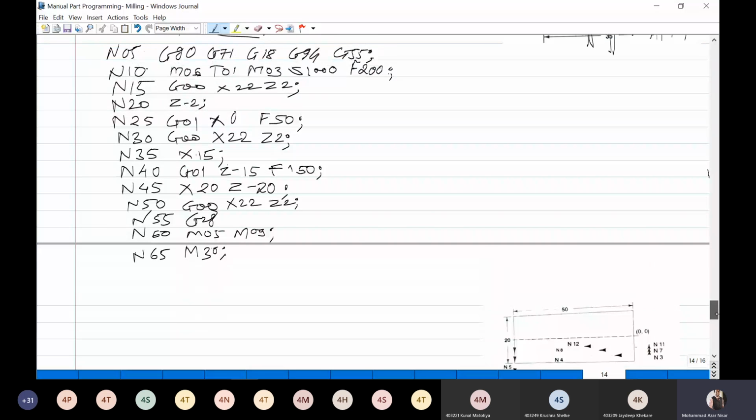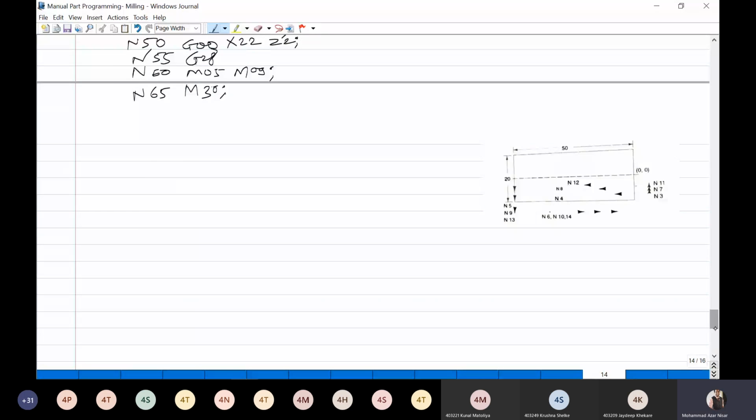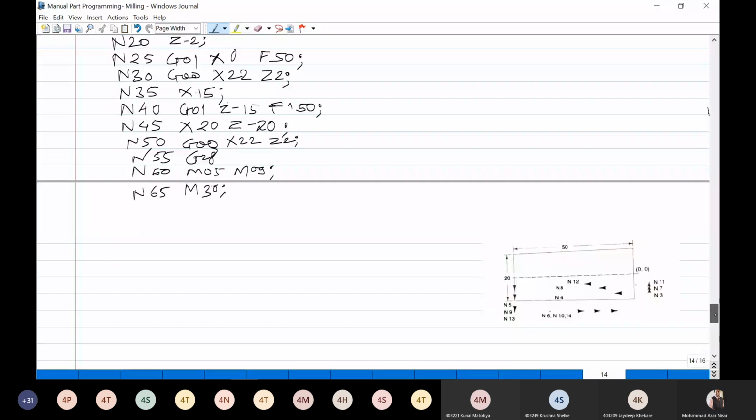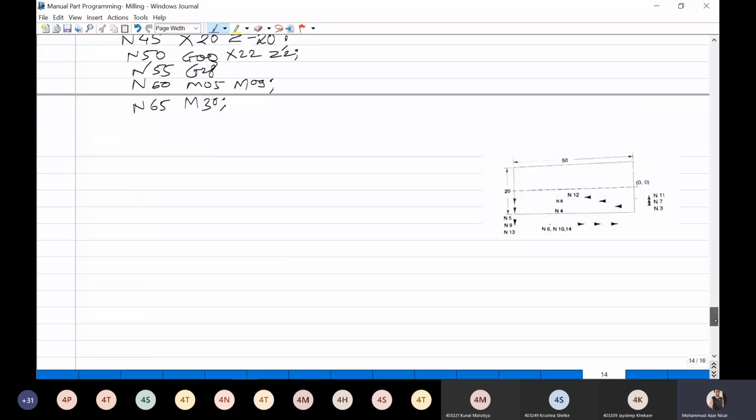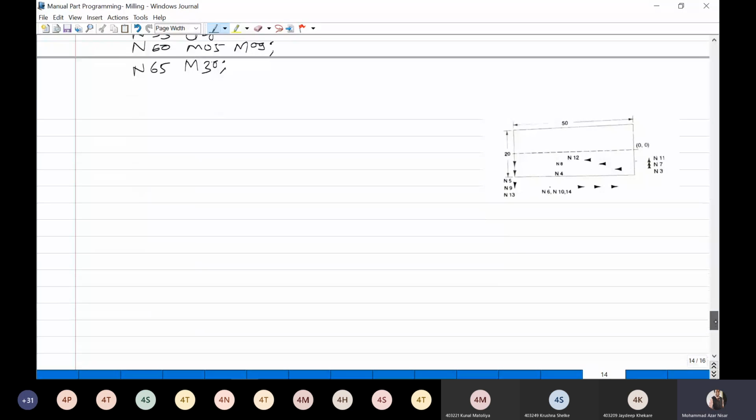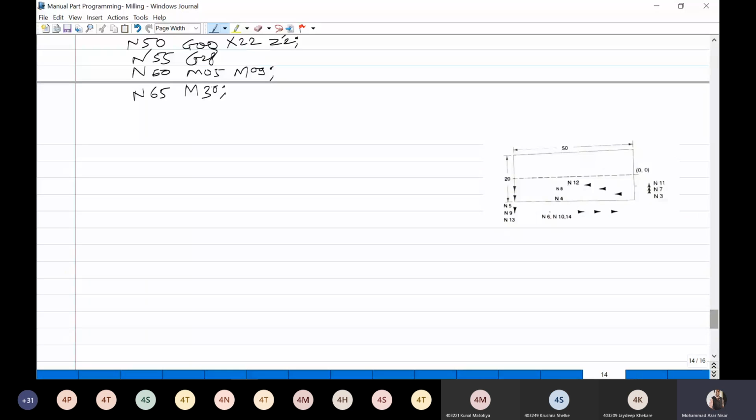So this threading operation is remaining, and the radius operation we will cover in the next session. So how to perform this threading and radius by using, in this we have to use K also. In both cases we have to use I and K, because J is not there, Y axis is not there, so I and K have to be used in both the problems. So we will discuss this.